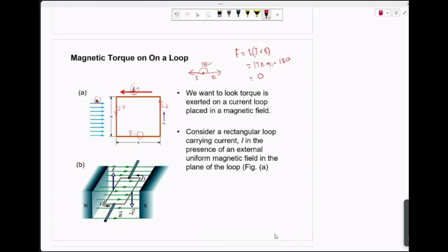Okay, so where is the direction of the force? Again, use your Fleming left-hand rule. Point out your index finger to the direction of the magnetic field to the right, and then bring out your middle finger, and while maintaining the index finger pointing towards the magnetic field, rotate your hand until your middle finger points towards the direction of current, which is downward there.